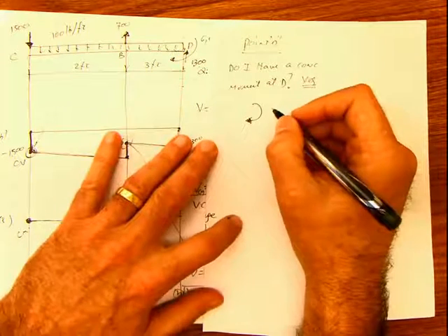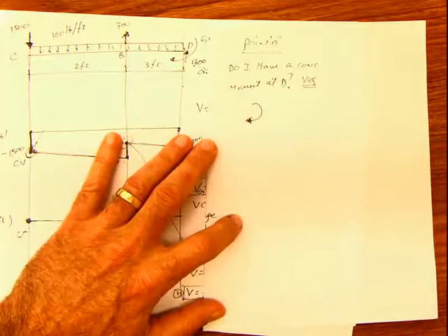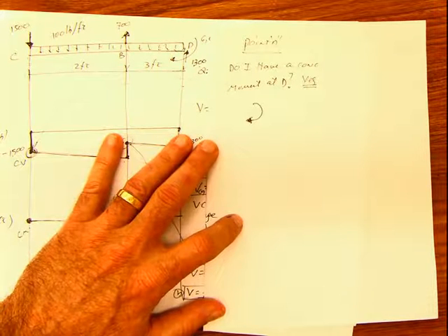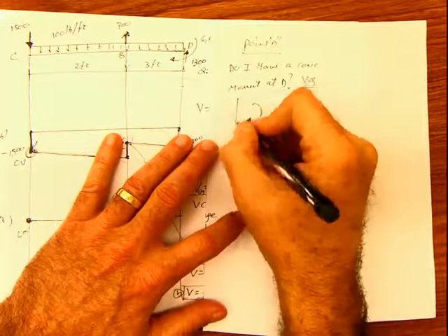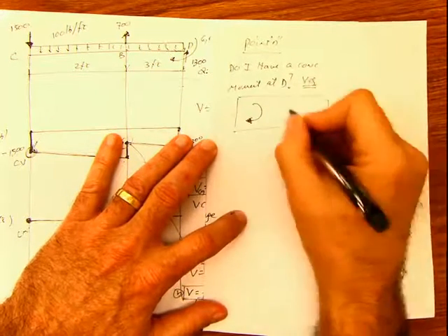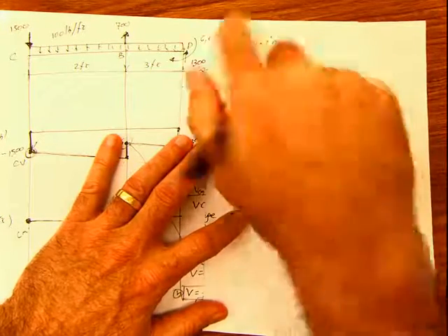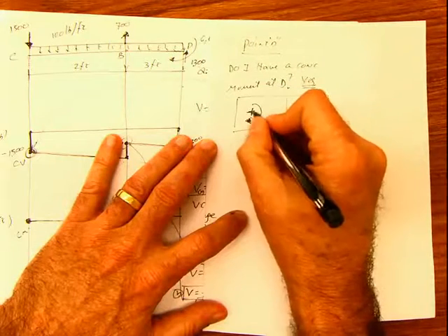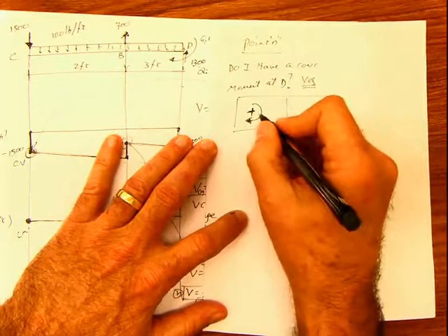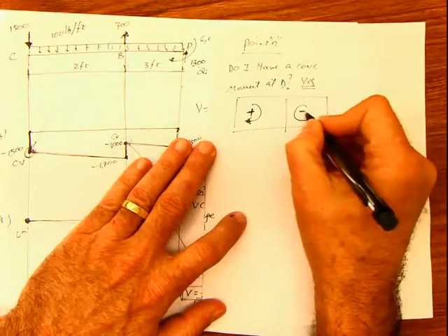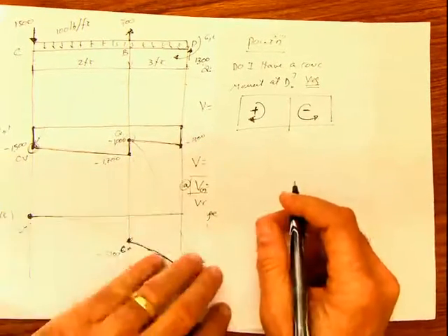Okay, this is new. I'm not going to say rule, but if we are using this type of plot for the shear moment diagram, you have to do it this way. Every time you see a concentrated moment in the diagram, if the moment is counterclockwise like that, you consider it positive. If the moment is clockwise, you consider it negative for the diagram, no matter what.